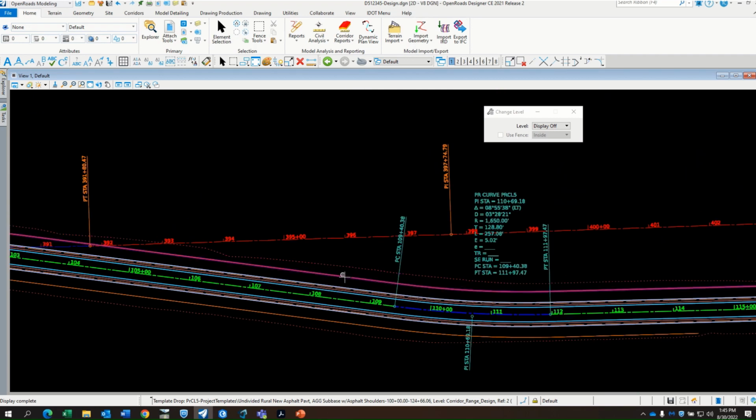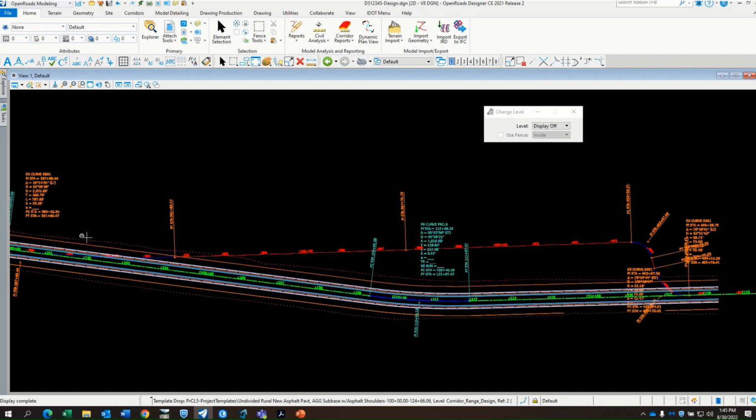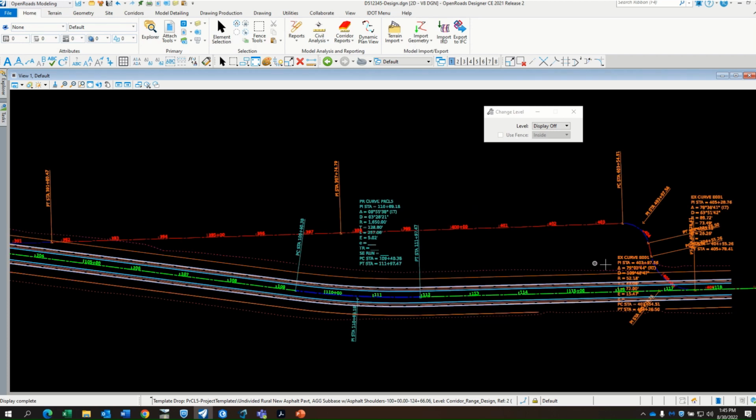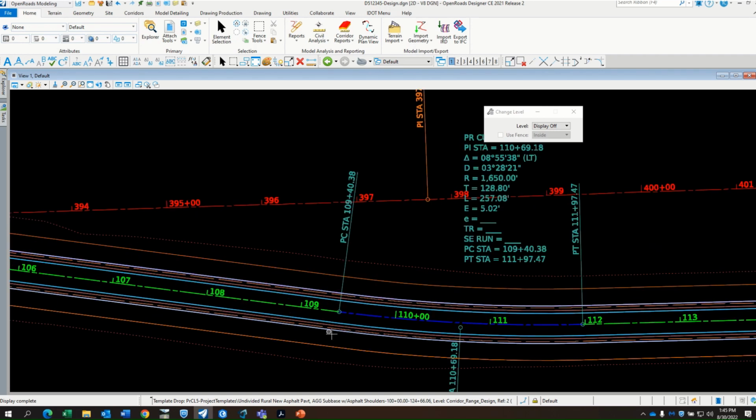And when we talk construction limits, sometimes there's confusion there. That's basically, think of it as where the back slope ties into the existing ground. Normally you have to develop your cross sections, and then you go in and you plot some points, and then it ends up being very segmented, that sort of thing. So you can see these are pretty clean construction limits. It also included this line. I think that's the yeah, there you go.